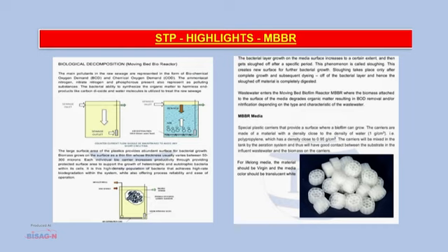That is polypropylene, which has a density close to 0.95 gram per cubic centimeter. The carriers will be mixed in the tank by the aeration system and thus will have good contact between the substrate in the influent wastewater and the biomass on the carriers. For long life, the media material should be virgin and the media color should be translucent.